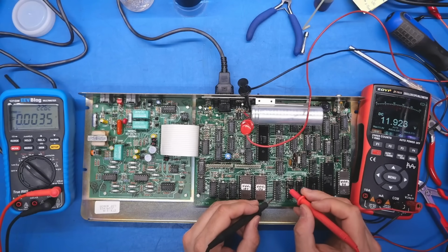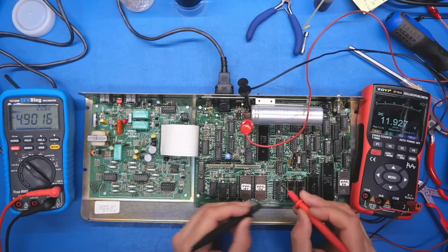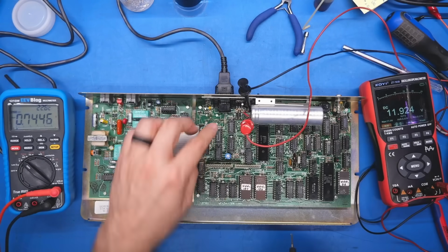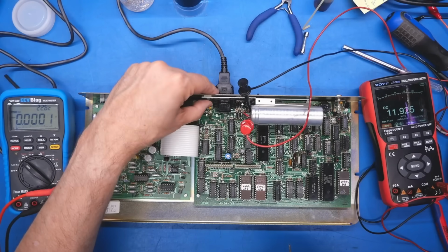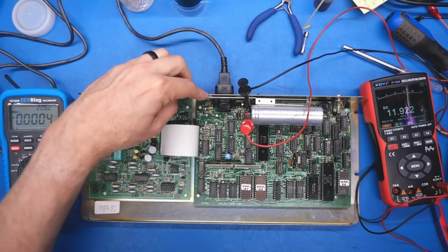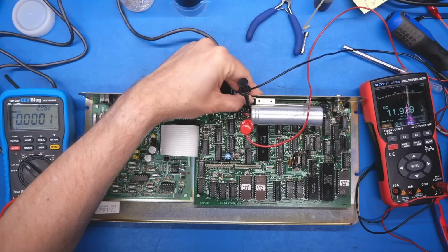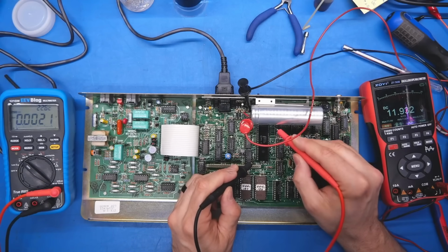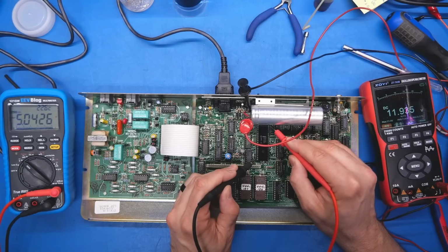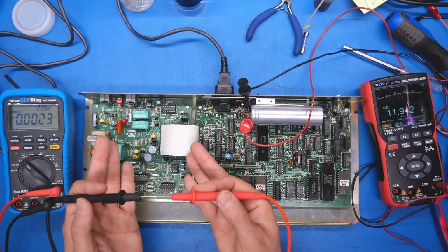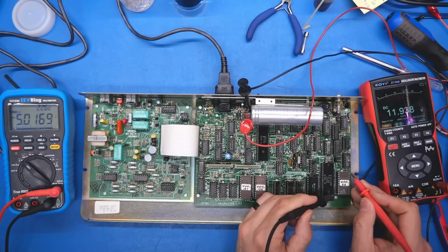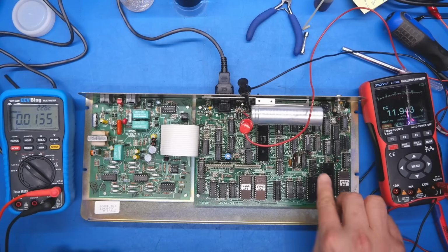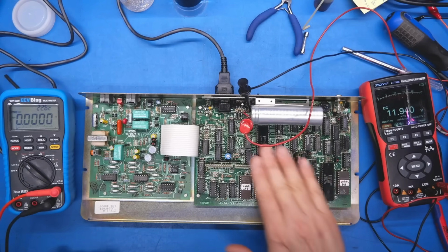Let's check a few things randomly. 4.9. How about on the CRT controller? 5 volts. Remember, these are 2 different voltage regulators. That one's warm. This is the one for the logic ICs, and this one over here feels like it's getting warm as well. That's the CPU. Let's check the CPU. Should have 5 volts here as well. 5.04. But no clicks. But maybe that's somehow normal. 5.01. So that's obviously fed by the same power that goes to the CPU and the CRTC.